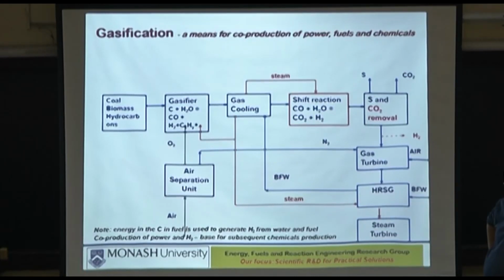Only if you give it oxygen. So what are the long chain hydrocarbons? C15, 16, etc. These will all come down to the shortest possible chain, CH4, unless you give it oxygen. So in the gasifier, at the exit, oxygen is 0, because all the little bit of oxygen that you have given to the gasifier, the substoichiometric oxygen, has all been used up. No excess oxygen in the gasifier outlet.